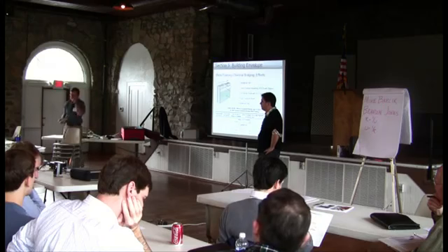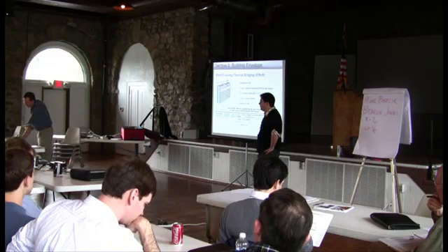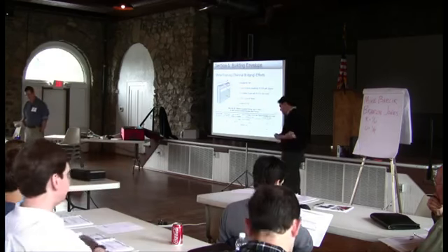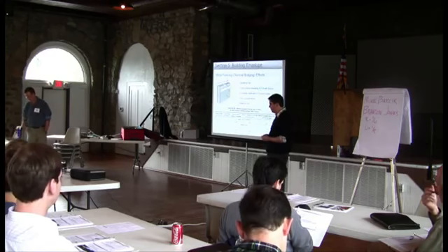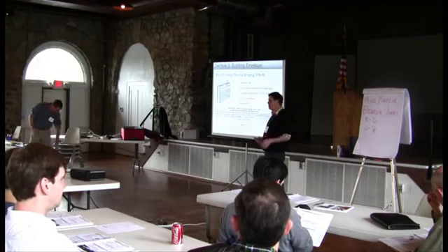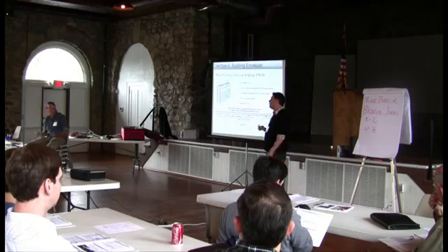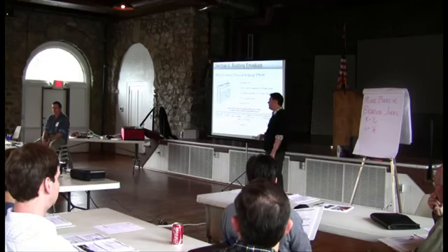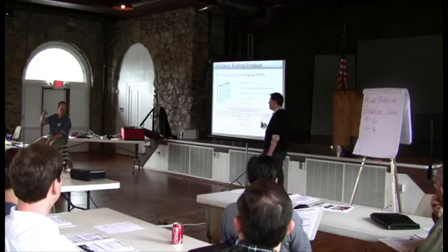Just to get the girth, because your metal siding would go right up against the... And that's an interesting point, though, too. So we've had previous discussions about metal buildings that are used as commercial spaces, where instead of using just the metal building structure as you typically have it, you've got this metal stud infill, which is actually going to kick it into more of a non-metal building. It'll be considered a metal stud wall. So your insulation, you actually have to do more.